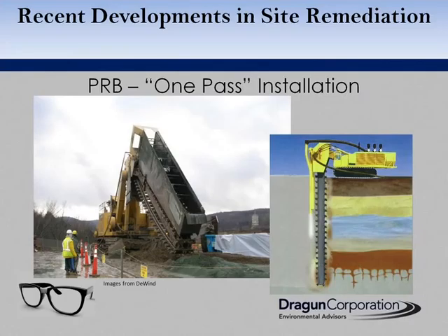They've developed a nanoscale version of zero-valent iron that is much more injectable. The other advantage of that type of ZVI is that it has more surface area and so can treat higher concentration plumes. The downside is, since there is more surface area, it gets used up a little quicker and has a shorter lifespan than some of the larger particle size ZVI.